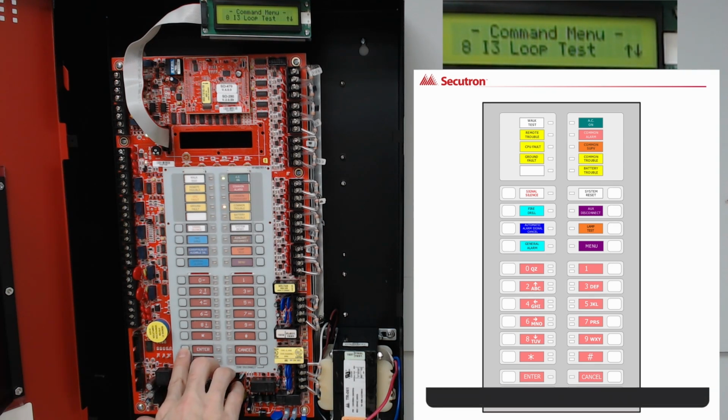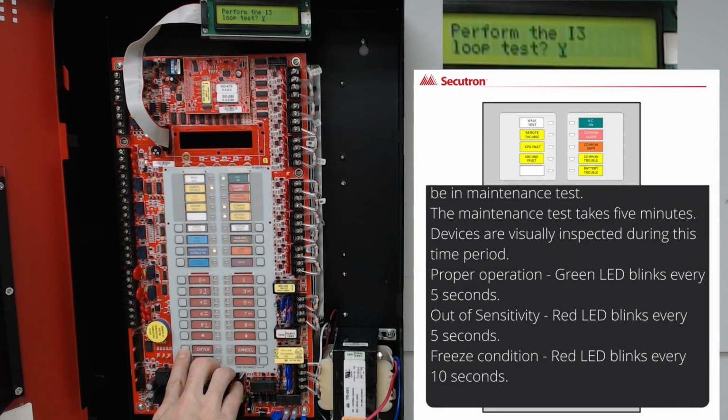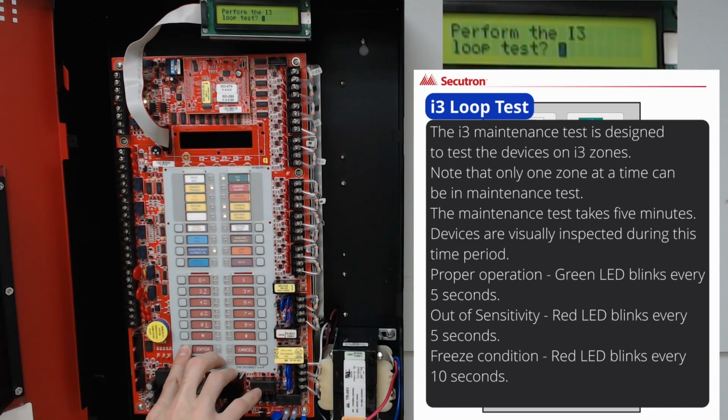Our next option in the command menu is I3 loop test. By selecting enter, we'll go in to perform an I3 loop test. The I3 maintenance test is designed to test the devices on I3 zone. An I3 maintenance test can be invoked from the command menu 6 minutes after power up or after pressing the reset. If an I3 maintenance test is selected, the screen will appear as such.